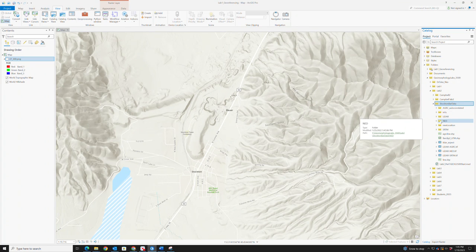National Elevation Dataset, which is older 10-meter data, and that comes from contour lines, whereas LiDAR comes from point clouds of lasers, and it's been filtered, I think, to bare Earth. SRTM is Shuttle Radar Topography Mission, and that'll be 30-meter pixels. And then this other one, AGRC Autocorrelated, is based upon imagery and stereo imagery, and that makes a 5-meter digital elevation model for the state of Utah.